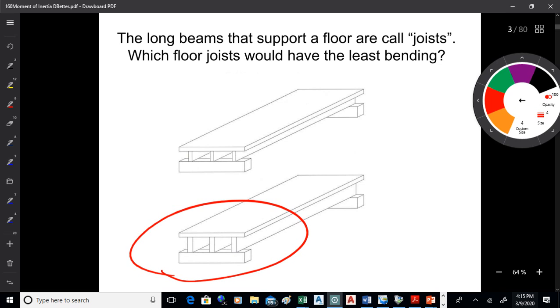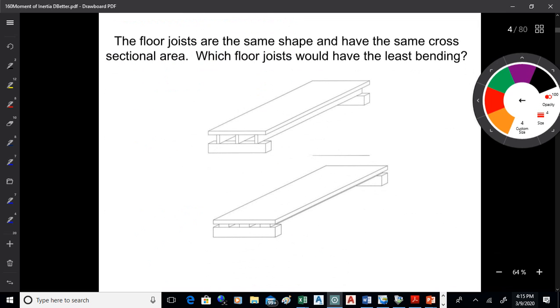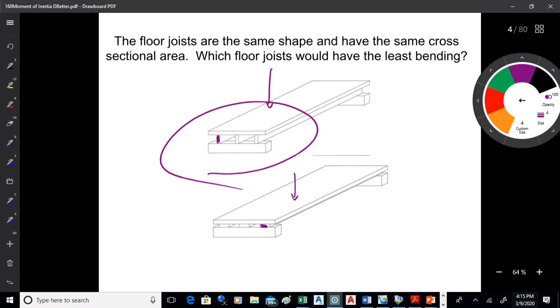Yeah, that's true. Now the material would matter, you're right. Okay, now those beams there are the same size, but how would you turn the beams to bear the load, top or bottom there? What's the best way to bear the load? Because the beams are the same size, and my point here is there's more than just area. Beams are more rigid on their sides. So yeah, the top one's going to hold more load than the bottom one, because it's got a bigger dimension that way, right? Here you got the weak dimension going into the load. There you got the strong dimension. So my point there is it's not just the size; it's how you orient it.